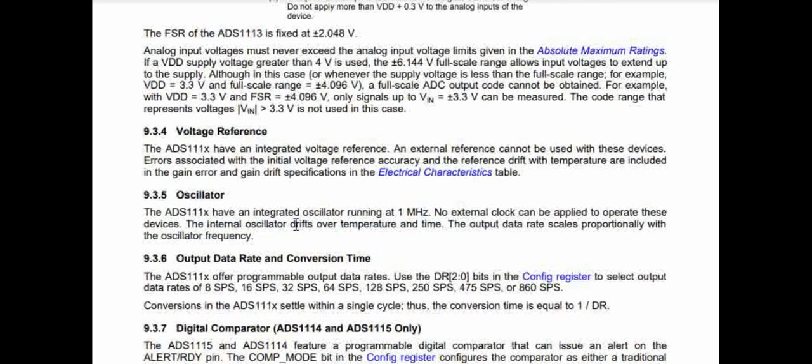The frequency tolerance, or basically the variance of this particular internal oscillator, is a cause of concern for engineers, where you don't have any control. You have to follow the specs provided by the ADC, and definitely there will be a variance with that, which actually varies the rate at which output is being generated from this ADC.